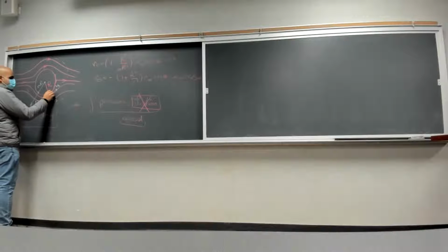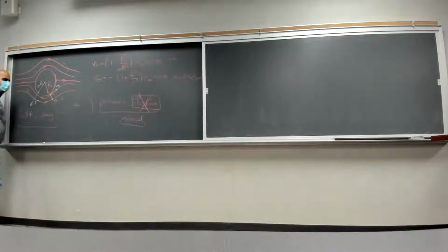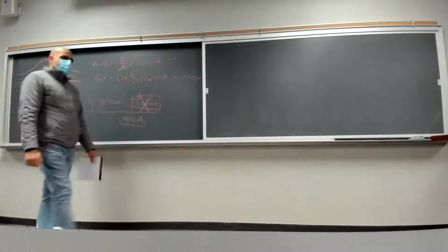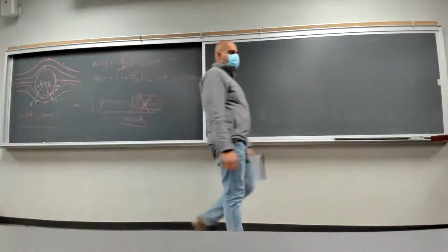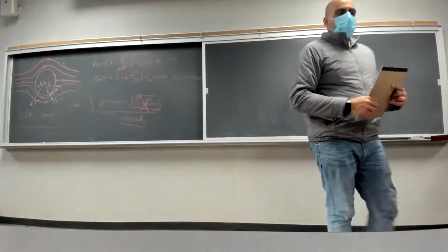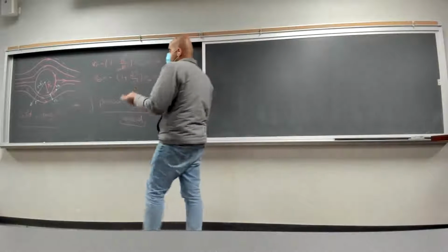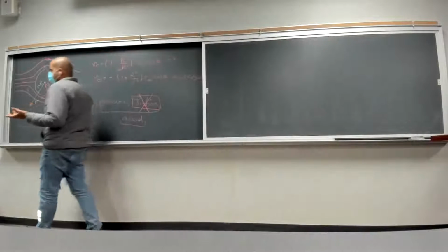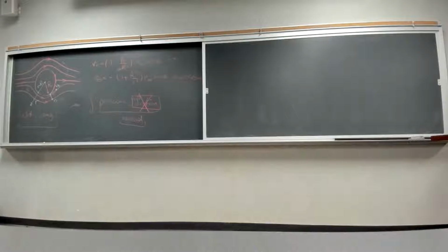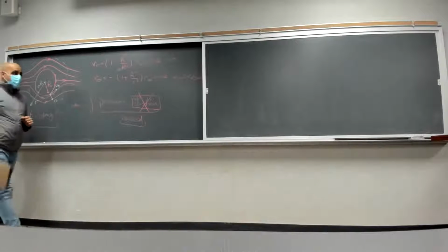So on the surface itself, there is no component normal to the surface. The velocity is always going to stick to the surface and be tangent to the surface. Since this is an inviscid flow, the velocity on the surface is not zero, it is non-zero. Velocity is going to be equal to negative 2 V infinity sine of theta.